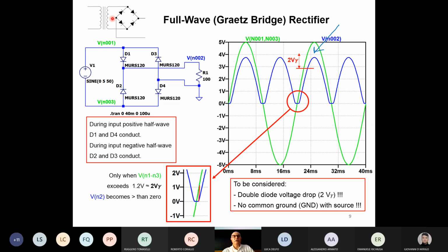It's very useful because it's using only the minimum amount of copper at the secondary winding, but you must accept the double voltage drop. If the output voltage is small, this error can be very large, and you have to consider it. If we are using a high voltage, you can neglect, again, this 1 volt voltage drop.